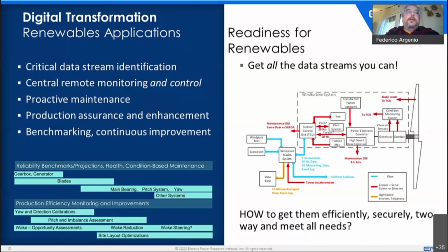Then, if it is possible, for doing the post-processing analysis, we reconstruct this data using, for example, an info provider for the ambient temperature or satellite data for the irradiance. If it is not possible, we have a system that will send an advice to the plant supervisor asking him why all of these data are missing, because obviously there is some information that the SCADA system cannot catch.